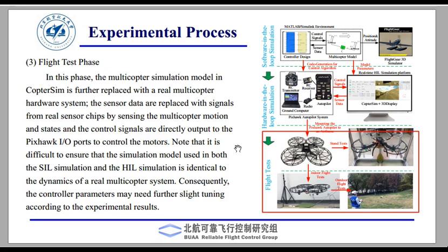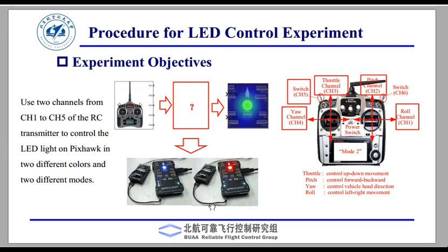Note that it is difficult to ensure that the simulation model used in both SIL and HIL is identical to the dynamics of a real multi-copter system. Consequently, the controller parameters may need further slight tuning according to the experimental results.